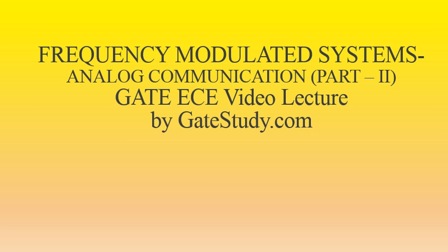We know that continuous modulation schemes are divided into two categories: linear modulation, that contains the AM systems, amplitude modulated systems, and non-linear modulation, under which the angle modulated systems come. In angle modulation, phase or frequency is changed according to the message signal. Angle modulation results in infinite bandwidth. Fortunately, most of the energy is contained in finite bandwidth.